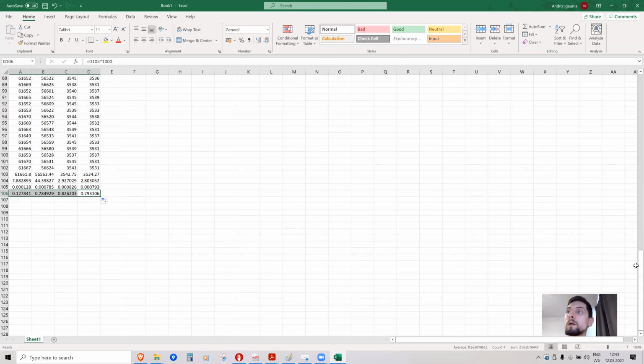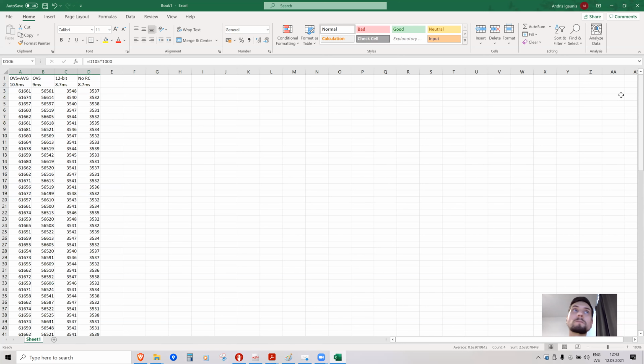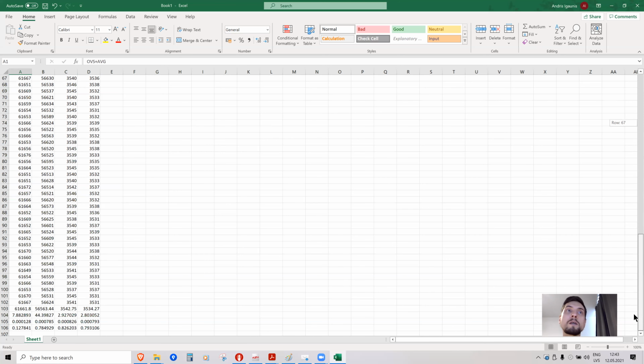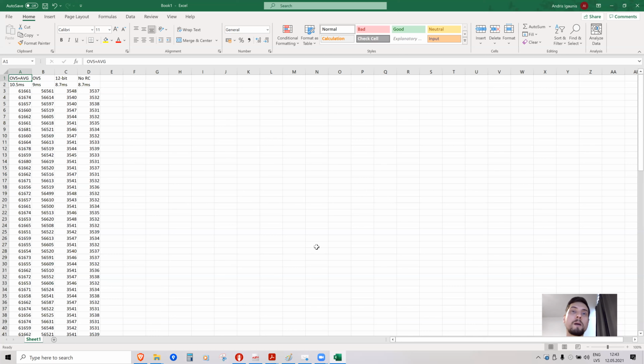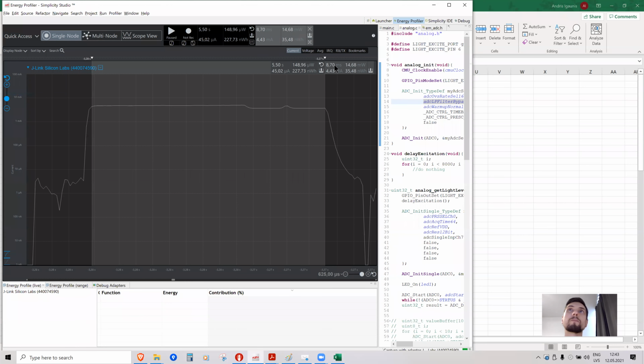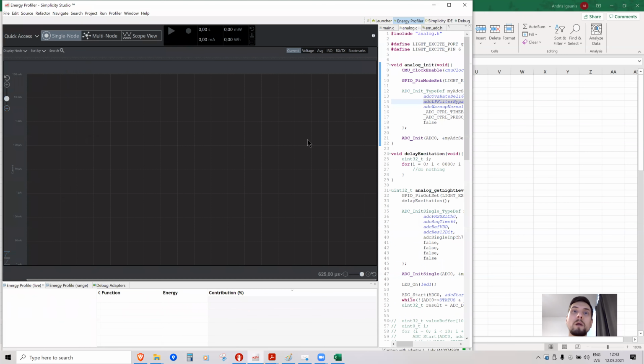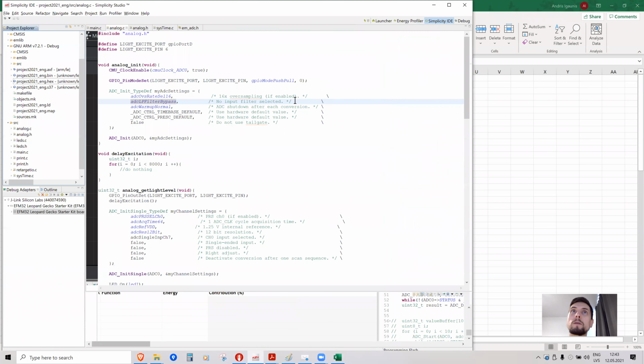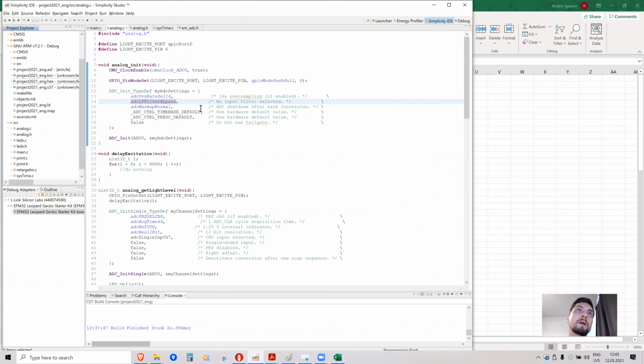And here we can see that oversampling plus averaging plus RC filter gave the best results. But RC filter didn't change much the signal, but it would change the signal much if the signal was more noisy. If you're sampling something over long lines, for example, you have to use some capacitor for decoupling. Okay, so that's all for this lab. We measured the variability and different sampling techniques.